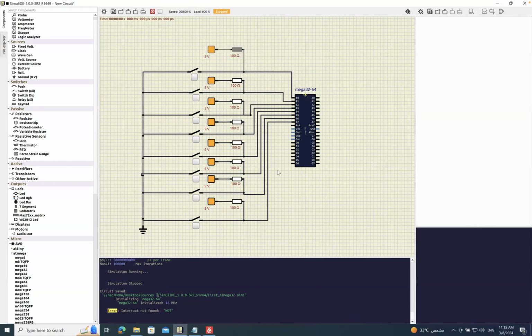Press copy, and here we can put them and connect it directly. That would be too far. This is good. Okay, and here we connected to the reset. So we connected port B to the switches and the reset pin to the resistance and VCC.